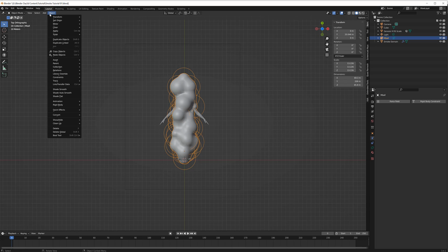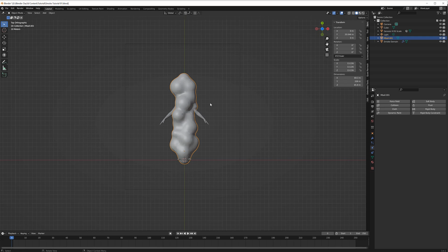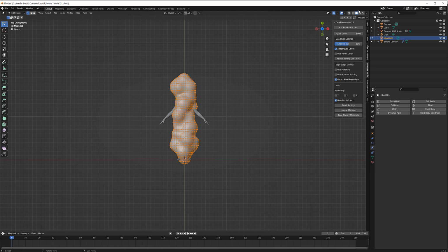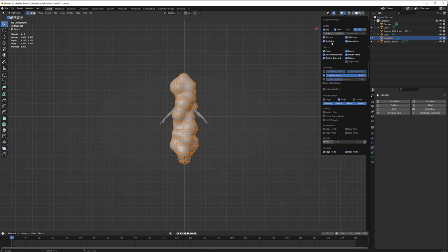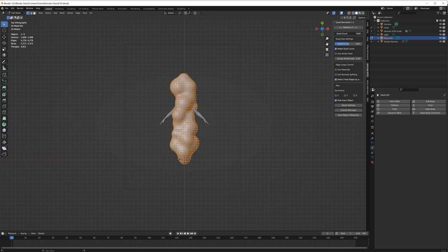I'm going to go to Object, Convert, Mesh. Now it's a mesh. When I hit Tab, it has square geometry. That doesn't look real great. I'm actually going to remesh that. I use a plugin called Quad Remesh. I think it cost me $50, but there are free ones you can get. There's different options you can use. This has about 2,000 polygons, so I'm going to remesh it to that size. There we go. I'm just using this as a proxy, so the UV doesn't really matter.